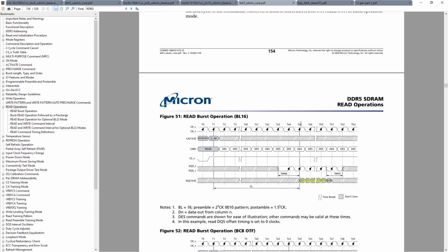Now, if DDR5 still used 64-bit wide memory sticks with its burst length of 16, instead of the two 32-bit independent memory channels, you would be getting sent 1,024 bits every time you send a read command. And reading 512 bits every time you want to read anything is not exactly the most efficient thing in the world,